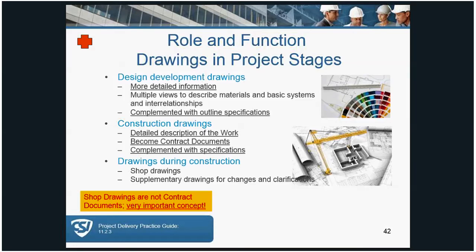The 100% CD drawing, along with the contract forms and specifications and contract modifications, form what are known as the contract documents. Note that the level of detail of the CDs will vary depending on the type of project and the delivery project method used. For instance, the design-build project may have less detailed drawings, for example, just some code minimum drawings.